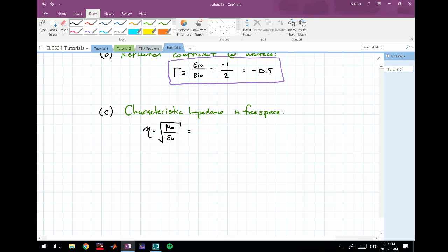When do you know to use epsilon E? Epsilon E, if you look at the definition, is defined with a conductivity. It has a sigma in it. If you're in a conductor, you will need to use that. Chances are you won't be in a conductor, because that makes the problem overly complicated. But when you have epsilon equals epsilon E, which is epsilon times 1 plus sigma over j omega epsilon, something like that, that only exists when you have this sigma, which is only in conductors. Because if you're in a dielectric, the conductivity is not good, so you can approximate this whole term to be 0.